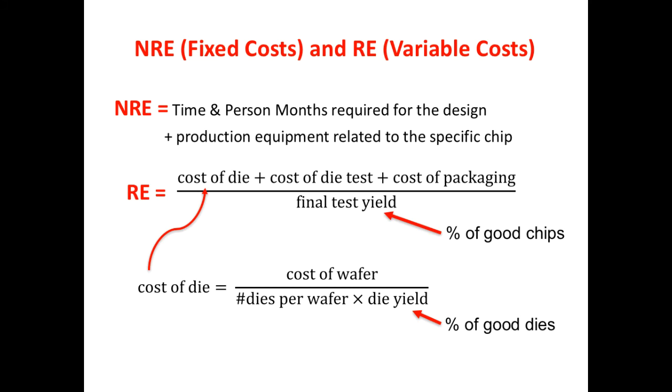Now up to 300 millimeters. For a long time there have been, let's say, discussions of using larger wafers of 45 centimeters in diameter, but then it seems that there's a problem: the cost of processing each wafer is becoming higher than the increase you have in the number of dies. So there's no reduction in the cost per die.